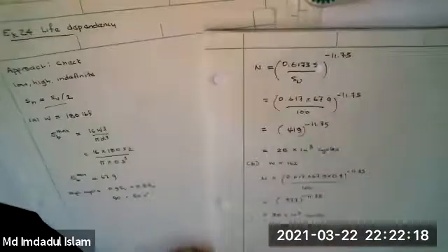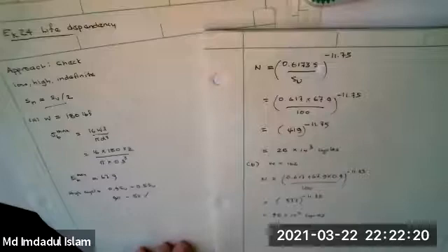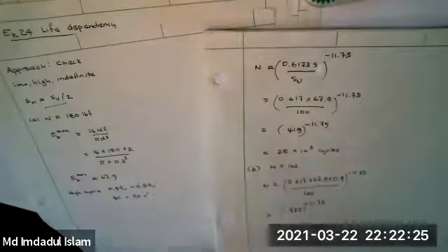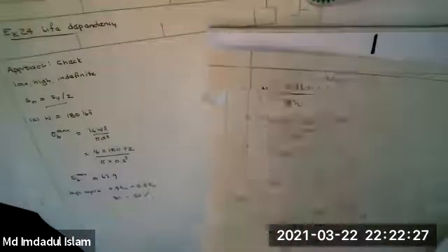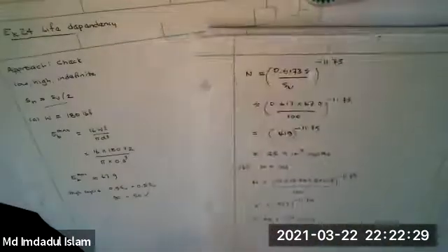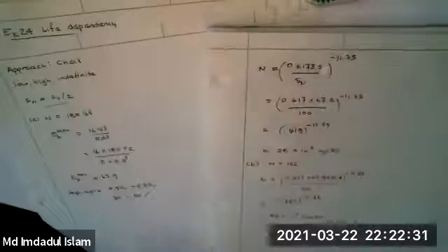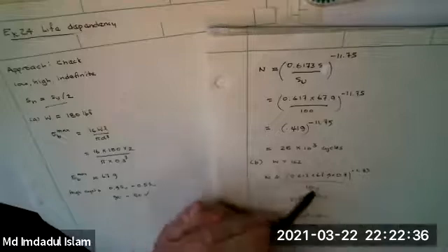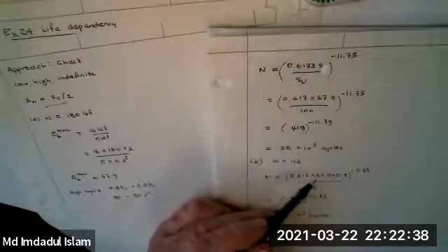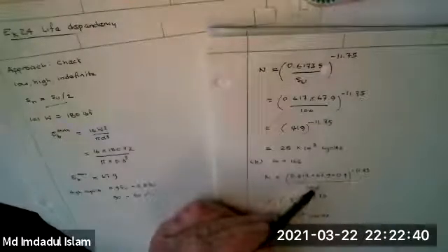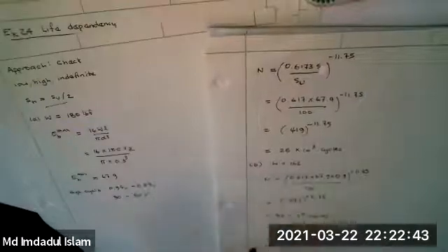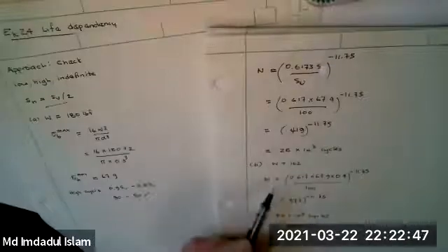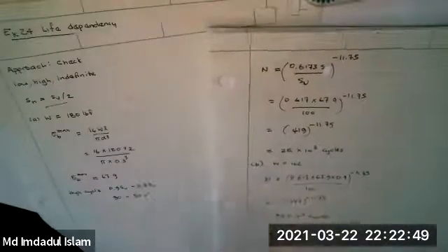So things are very sensitive to the load for these steels, in general, in metals and practice. And so what we had here was a 10% drop in load, and you got 3 times the life. Actually, it could have been more than that. This goes down to 61. If it had gone down below 50, we would have had indefinite life. But let's assume they both stay in the high cycle region, which is a common thing. Then here we've got a factor of 3.